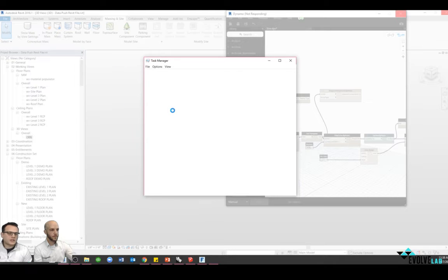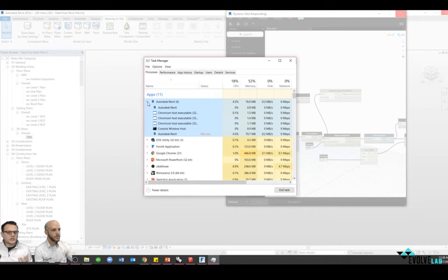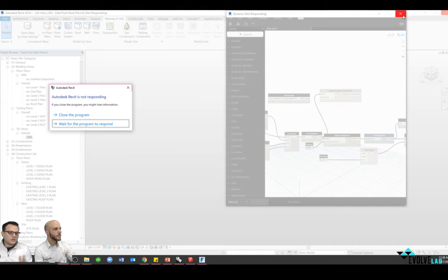the staticness of the DWG once it's imported, it also brings in all the line types and line styles. There's one consulting engagement that I worked on years ago. They were doing three things that were just destroying their models, and they were having such latency issues. One of them was they had imported a bunch of DWGs in the background for their landscape or their topo, and essentially they brought in probably somewhere around order of magnitude 4,000 line styles.